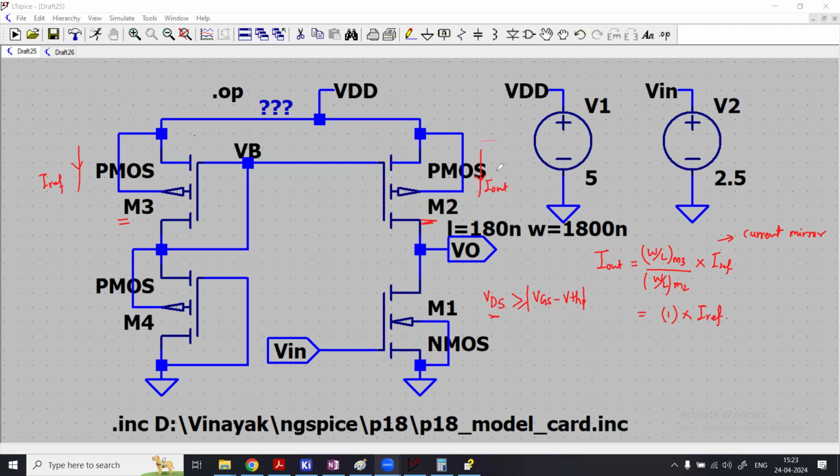be greater than minus 1.5 volts. So it should be, let's say, minus 1.6 onwards. Okay, that's the negative voltage polarity. Only then will M2 and M1 be saturated, and that's the condition for maximum gain offered by the circuit. Okay, so how to identify and how to use that